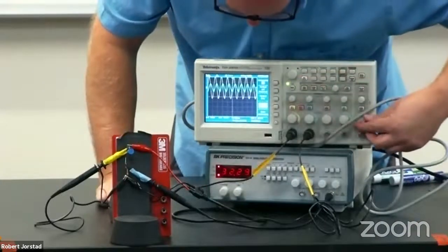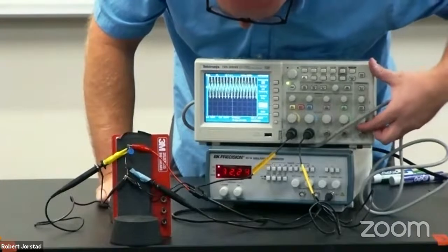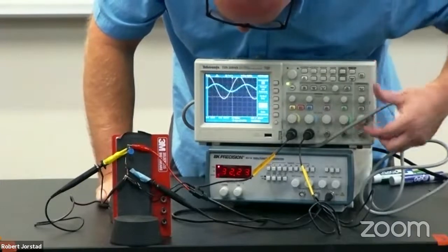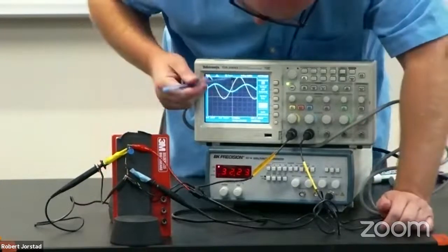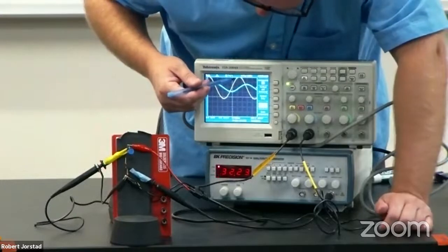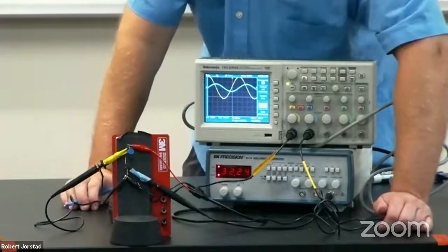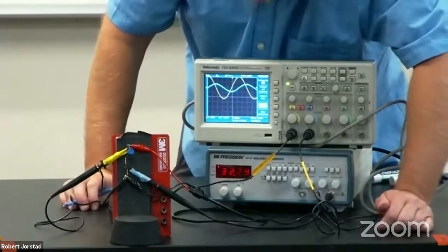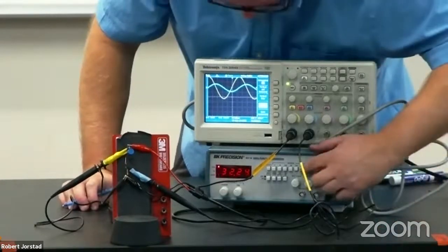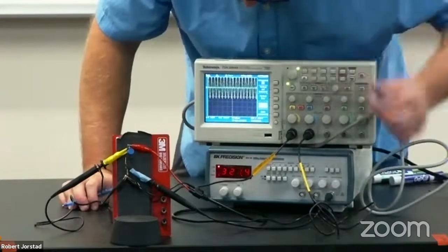if I change the scale, so if I go to a slightly higher frequency, now it's switched. I see that the source voltage is peaking before the current. So this is exactly what we were expecting according to the graph up there. All right. Now, as I go to higher and higher frequencies in auto range, the current goes to 0 again.